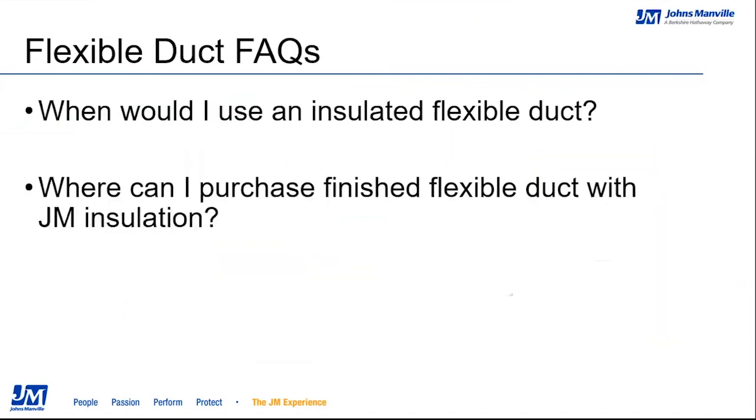So flexible duct FAQs. When would I use an insulated flexible duct? Please note flexible ducts are primarily used in residential or light commercial applications. In addition, you would use an insulated flexible duct as it is an efficient way to tap off from a main trunk line duct to connect to registers and diffusers in an effort to get air with minimal or zero air leakage from the HVAC system to occupied spaces within the home. As stated earlier, typical flexible ducts are on average 25 feet in length and are an easy way to quickly finish a light commercial or residential system.